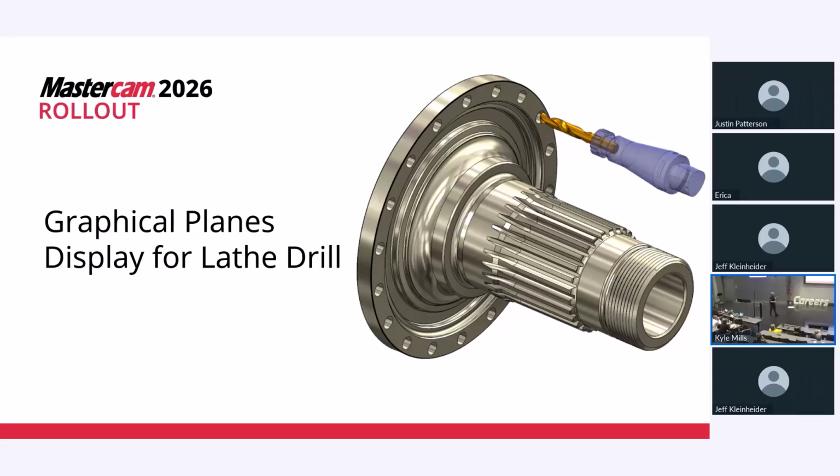So on this, picking that depth is sometimes hard, especially when you're on a subspindle. Am I going positive? Am I going negative? How am I working this? If it's a mill turn with a B-axis head, how do I need to put that into the software? Those graphical planes really just eliminate those questions because it just shows you exactly where it's going to go before you hit go. So that's a really nice addition.